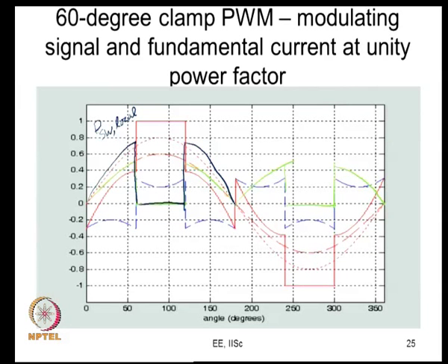So, what has happened between here and here is that there is a difference now. Here it increases by 1.5 times. Why? Because it is being switched at a higher carrier frequency. Here it is also at a higher carrier frequency. Here also, if you look at the average switching loss, you average this PSW local over a half cycle, you are going to get the actual switching loss.